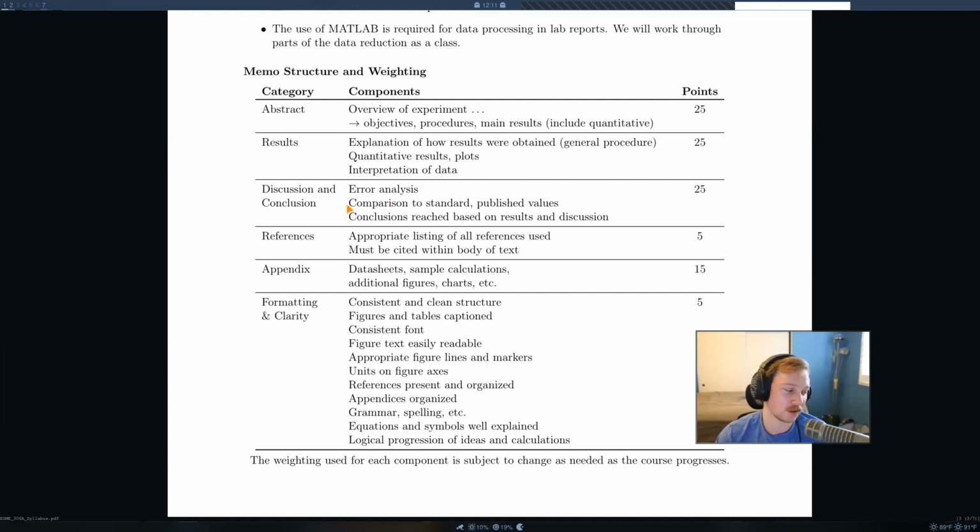Most of the error that we're going to have in this lab is going to be from equipment failures. Maybe not failures, but issues. So remember I talked about the end fixtures for the column lab? Sometimes those get damaged, and the way the loading is, it's not axial anymore. It might be kind of coming in at an angle, and that's going to mess up your experiment. Or maybe the extensometer for the first lab, that might not be centered correctly, which we'll talk about once we get to the lab. But if that wasn't positioned correctly, well, that is human error there. But also you can say that because it was positioned wrong, that it was affecting the results, and this is how.